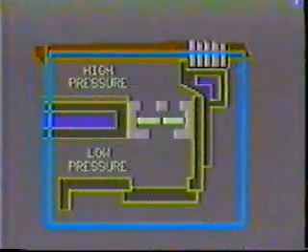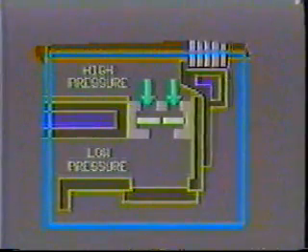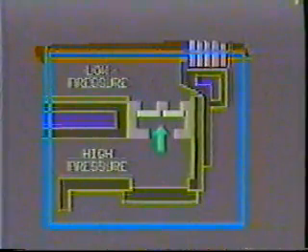To open a discharge valve, the gas pressure inside the cylinder must exceed the gas pressure inside the discharge gas jacket. Again, when the pressure relationship reverses, the springs close the valve.